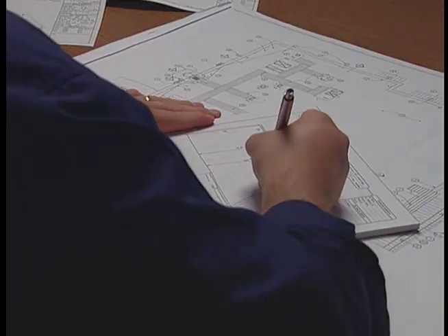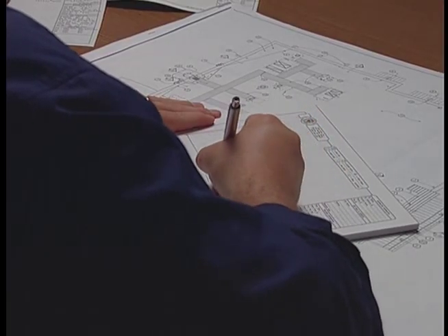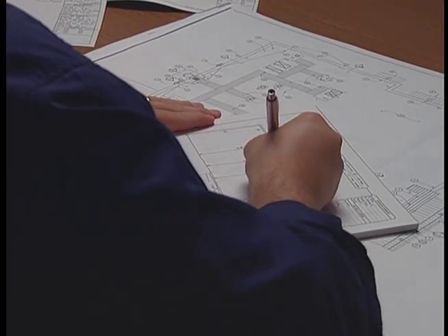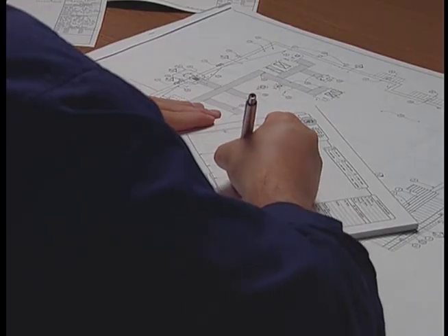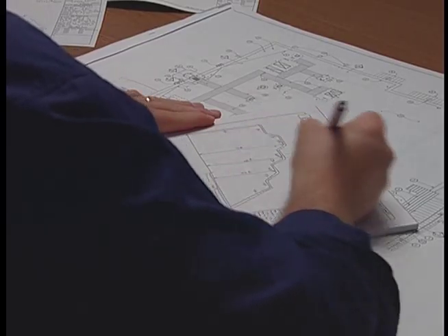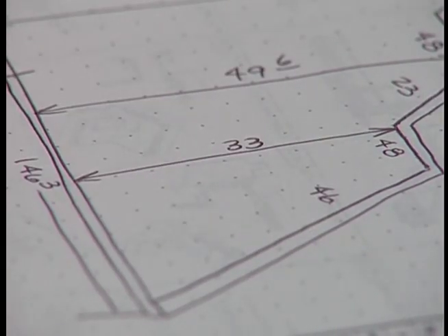Take another look at your sketch to make sure that you have all the needed dimensions. Be sure to include cross dimensions that might help to locate specific points. Determine cross dimensions by measuring from perpendicular edges. This is useful in all jobs and is required for roofs with angles other than 90 degrees.